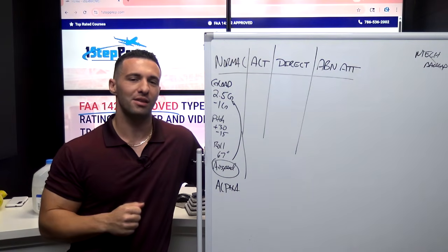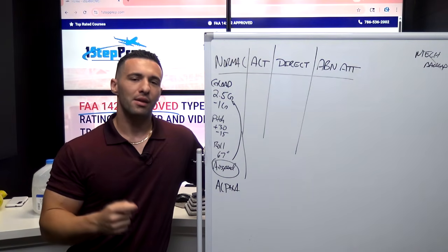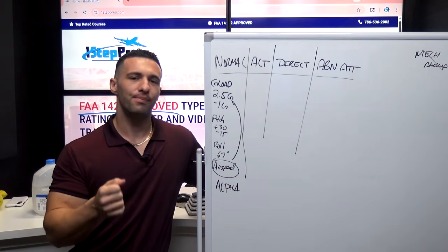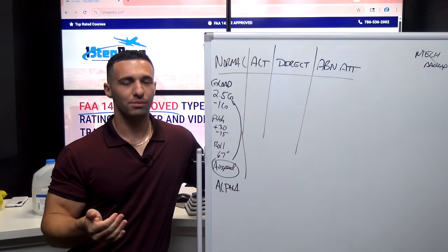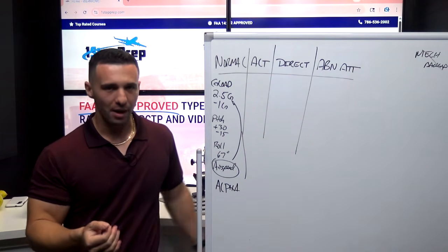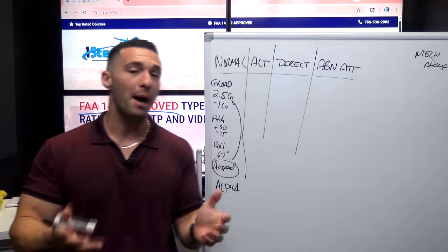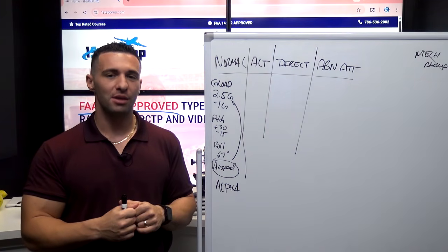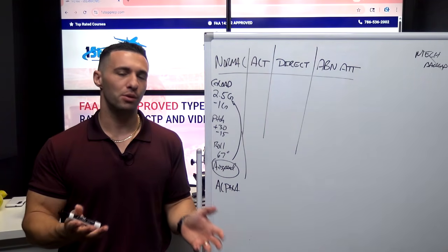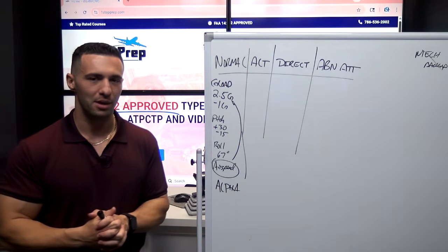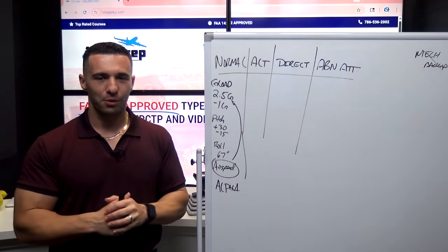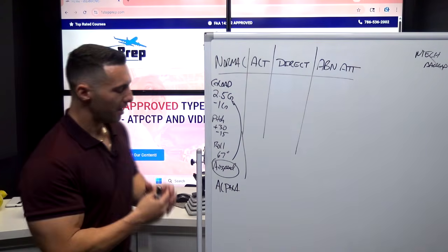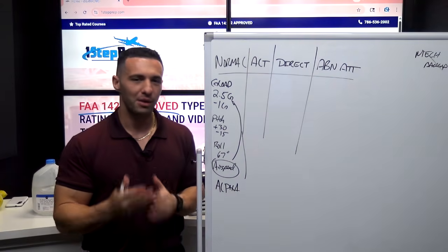So the autopilot disconnects. The next thing that happens is the side stick is actually now commanding AOA as opposed to G load. So we're going to look at that a little bit more. And the spoilers will stow automatically if you happen to have them out. And finally, the pitch trim in the nose up direction freezes. You can still trim nose down, which would help in the recovery of the stall, but I can't trim nose up. And for those of you who like acronyms, I realize our industry is full of them, but there is an acronym, it's ASAP, that more clearly articulates alpha prot and how exactly it does what it does.